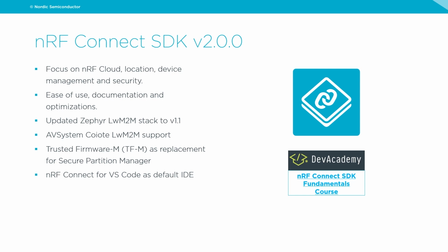On the nRF Connect SDK version 2.0.0, the focus has been on nRF Cloud, also on location, device management, and security too. We also had a big focus on ease of use, documentation, and a few various optimizations. So just some of the main highlights: we did update the Zephyr Lightweight Machine-to-Machine stack to version 1.1. We have AVSystem Coiote Lightweight Machine-to-Machine support.